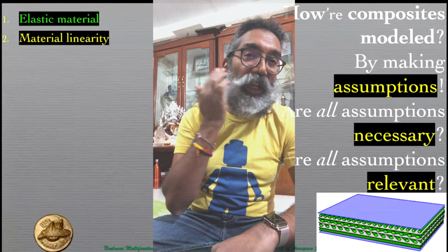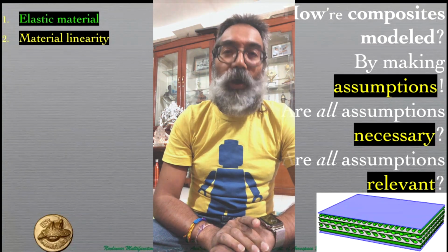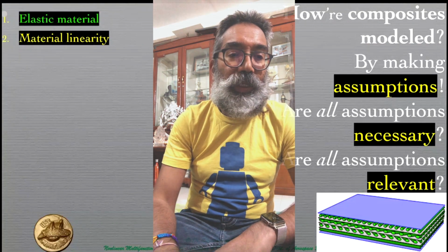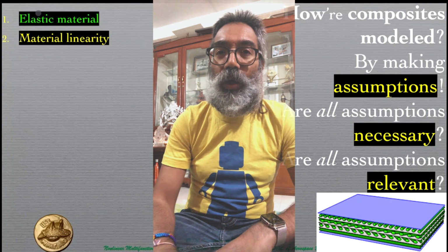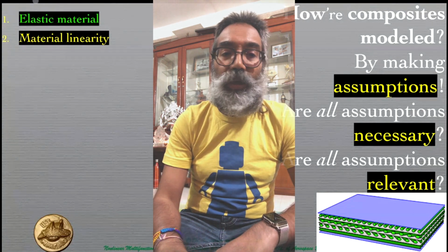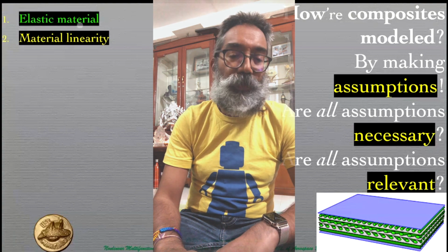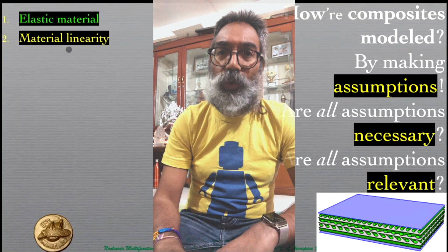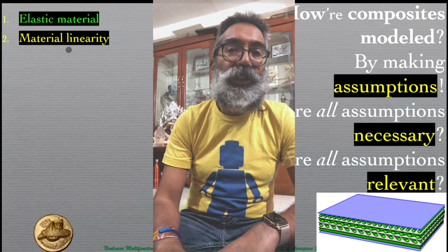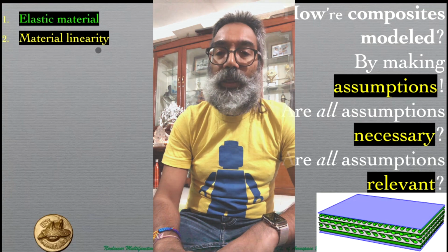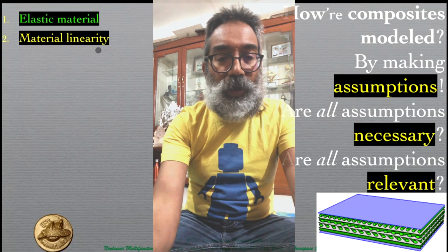But of course, if we are dealing with metal matrix composites or metals per se, we need to look at the elastic assumption also to some extent. But for many things that we'll be deriving, the elastic material is a reasonably good assumption within the scope of this course. And material linearity is also. But for a few applications in flight vehicle structures, you have to go beyond this material linearity. So now let's again come back to...